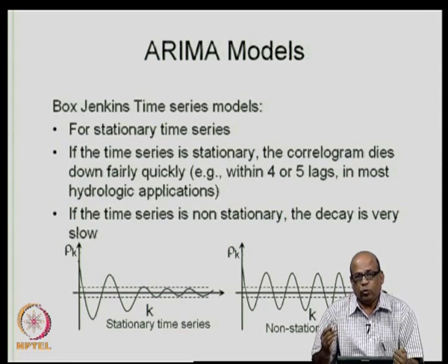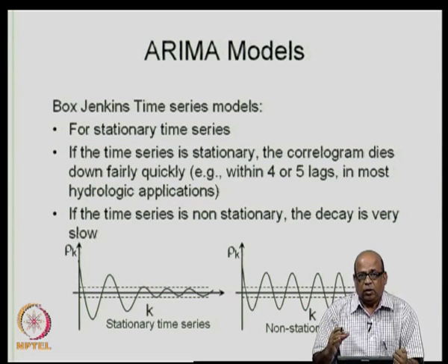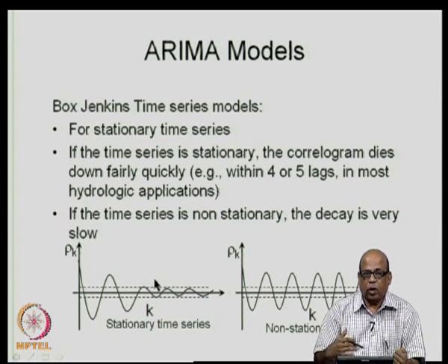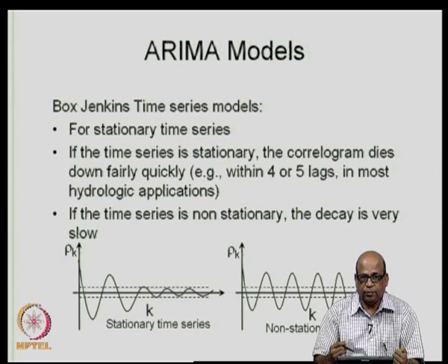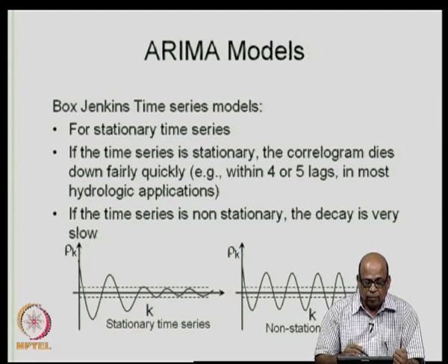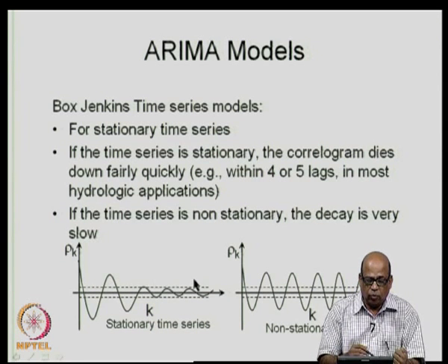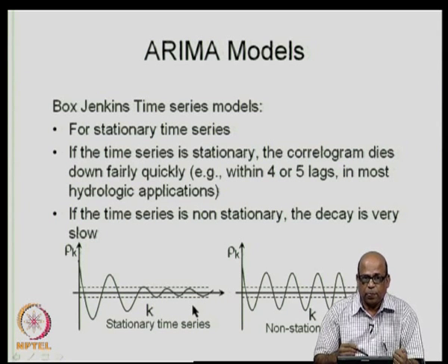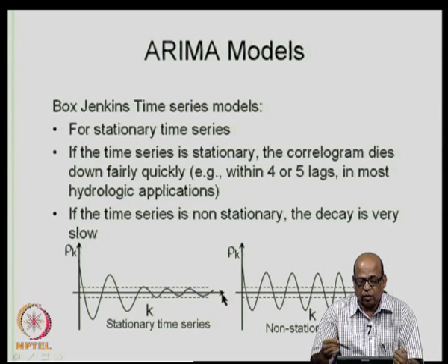In most hydrologic applications, you may see that the correlogram dies down after 3 or 4 lags, or 4 or 5 lags. By dying down, I mean that the correlations become insignificant as lag progresses; they become quickly insignificant.